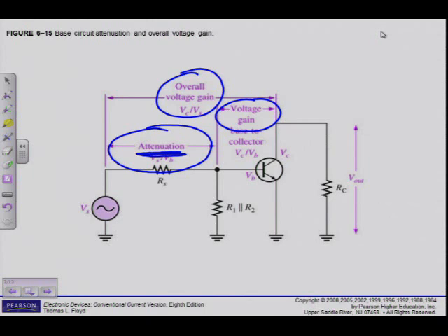Firstly we took our amplifier circuit and drew the AC equivalent circuit. Remember, because of the way the capacitors and the DC supply act, all of them acted as shorts. Can you recall?